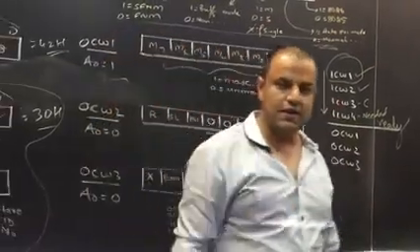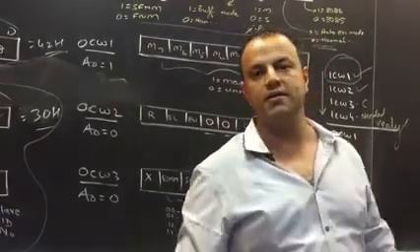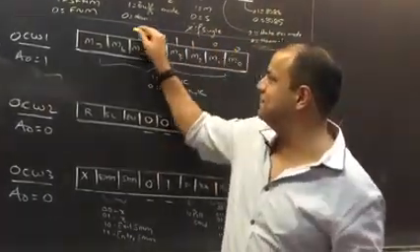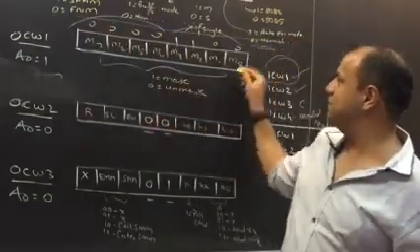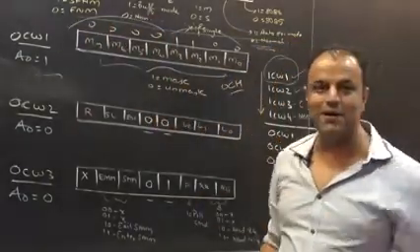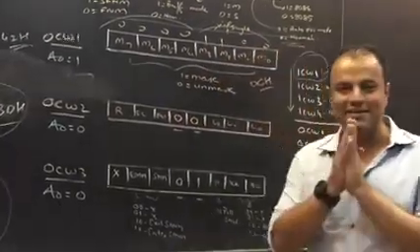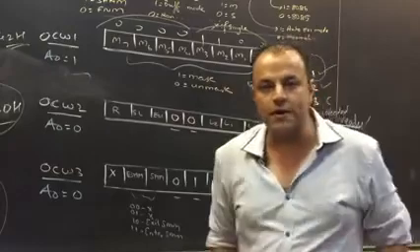So the question will say very clearly, mask IR2 and IR3 as an example. If they say mask IR2 and IR3, keep these two bits as 1, keep the other bits as 0. Your number becomes 0C, 0CH is your command. Give me my marks. Come on, it is so simple. This is what gives you marks in the exam. Anyway, did you understand this? So that's OCW1.